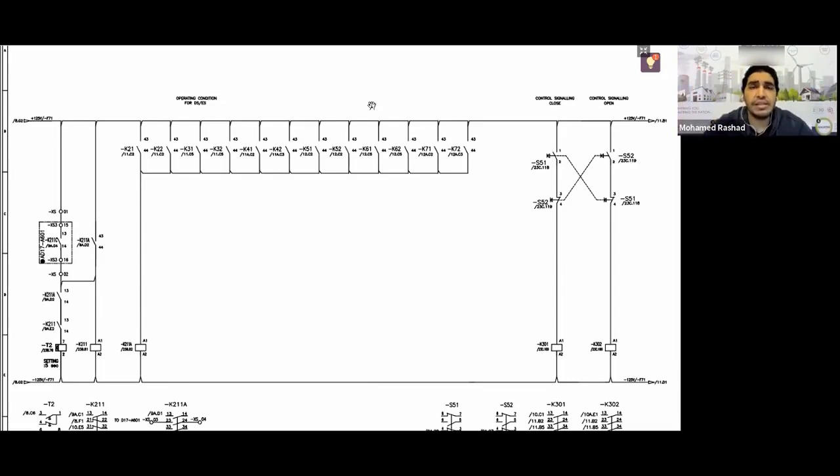The important idea here is the term double operation or double command, which means it is not allowed to give two commands to two different pieces of equipment at the same time. Only one piece of equipment can be running at a time. Once it finishes its task, you can then give a close or open command to any other equipment.